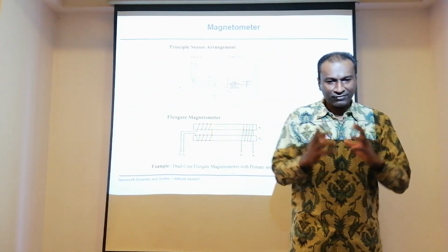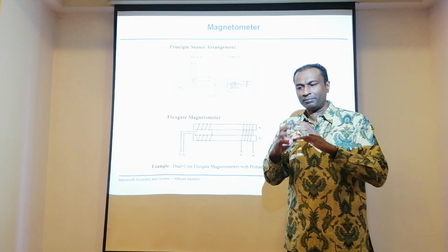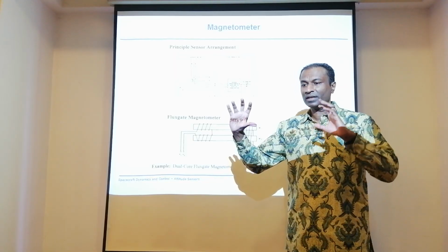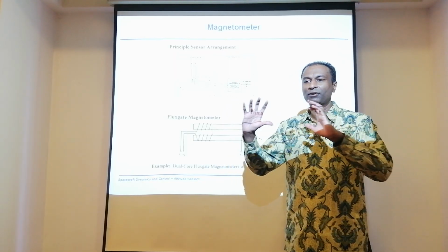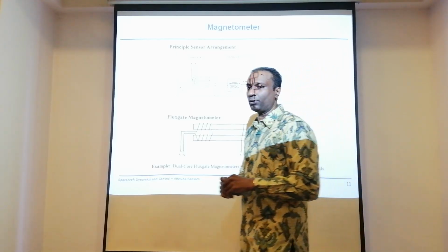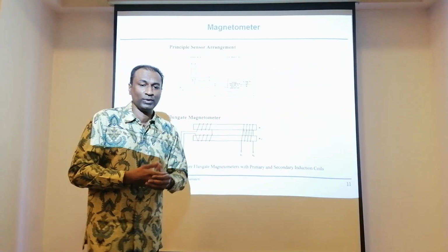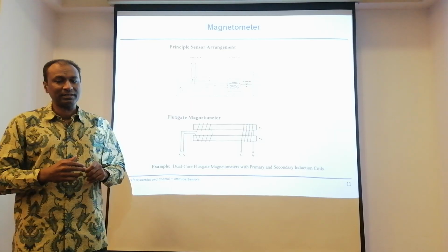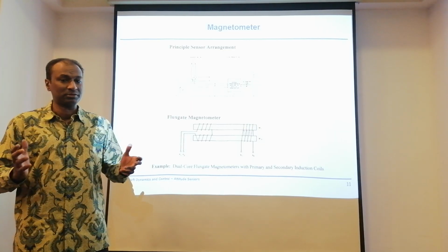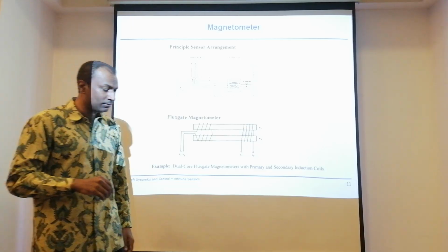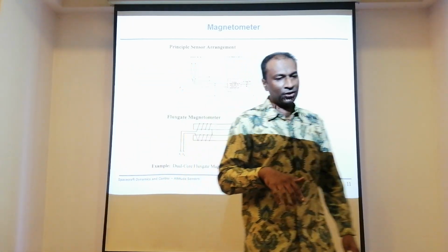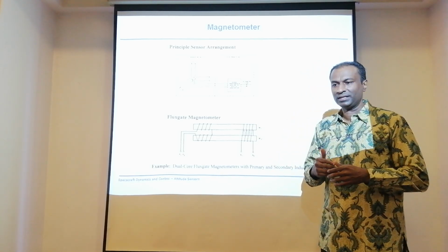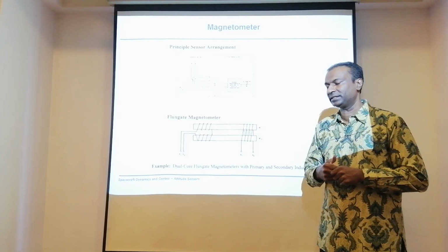Once we have the variation of the magnetic field, we have a complete model, the IGRF model, as I mentioned just now. We can compare, and once you start comparing, then we know exactly what our attitude would be. We should be able to estimate all three axes. But we can't always estimate all three simultaneously, depending on the orbital motion. But as we have learned before, at least two per cycle are highly accessible.